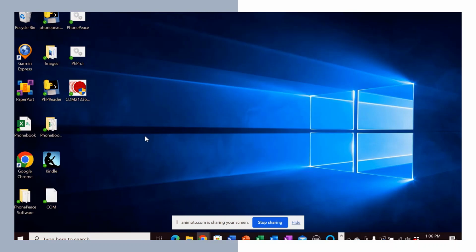If you still can't transfer data and the COM port number shown on the screen does not match the number from the Device Manager screen, you may have more than one USB port. Usually, the computer selects the correct COM port number, but if it doesn't, the next section will describe how to fix that.